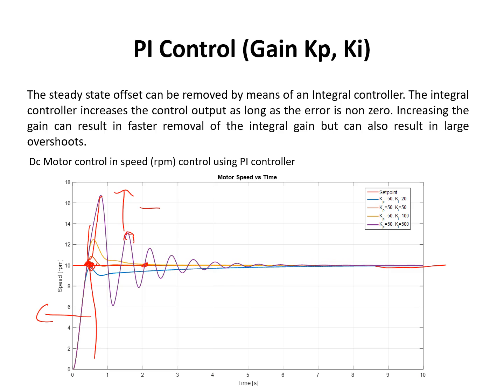So that's a problem with having too much integral error. An integral error term will always generally introduce oscillations in your system, or increase the overshoot of your system. So if you have a P controller and it has some overshoot, by adding an integral term you typically always will have an additional overshoot.